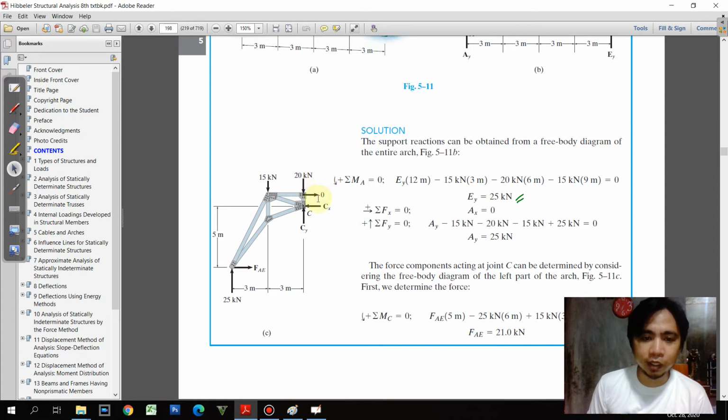So this is being cut, and it was already stated in the problem that this member will carry no horizontal loading, and usually this top member here has no horizontal force since there is no lateral force applied here. So that is the treatment, and usually most of the loading will be carried by the arc here.